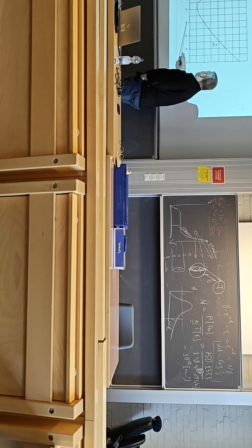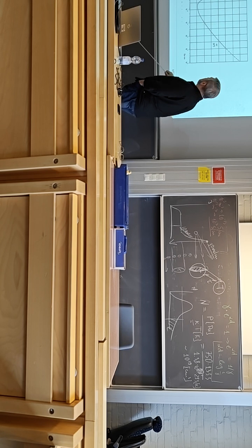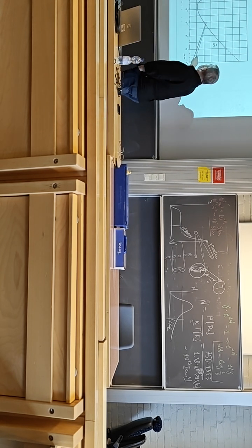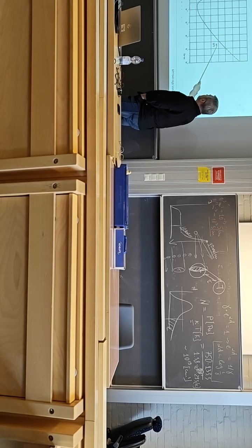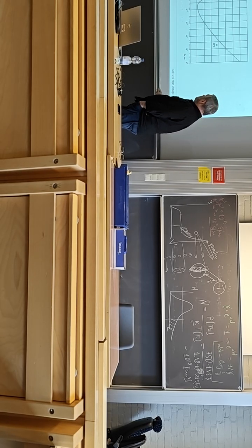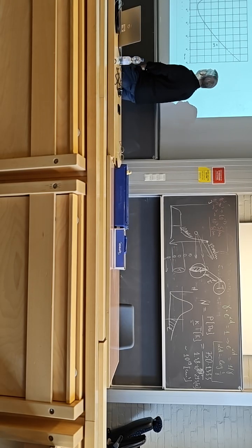So this is the product of P times d, bar millimeter here. Okay, let it be millimeters. And this is the breakdown voltage. So usually the curve looks like that. This is for air, 20 degrees C. So it has a minimum here.